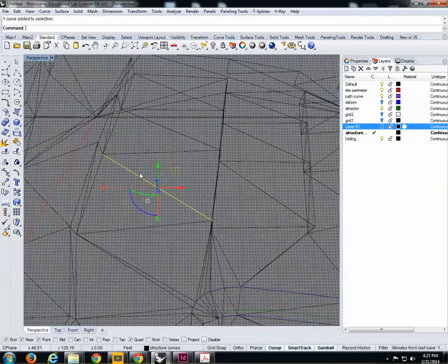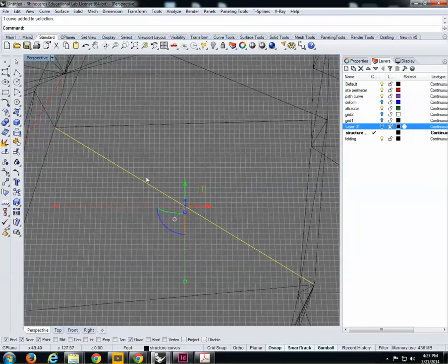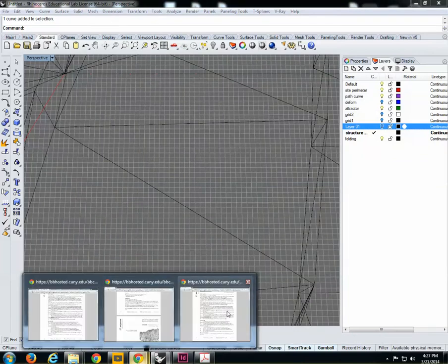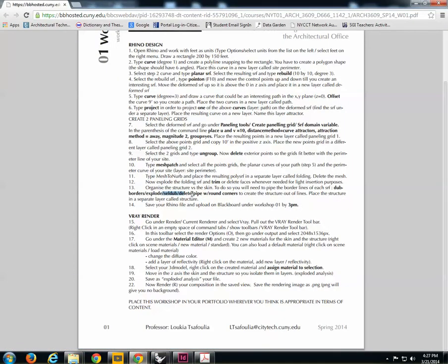And if I zoom in and select again, I realize that I only have one curve now. So select duplicates is the command for you guys to start deleting information that is repeated in your scene. Okay, not this one, this one. Okay, I'm done with that.